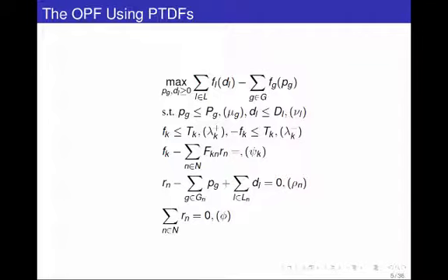So R as well as F are unrestricted in sign. There's nothing that imposes that they be positive, non-negative, or non-positive. So basically this equation is all of last lecture. The reason we bothered going through all the stuff we did last lecture is to get these linearized equations that map injections to flows. You tell me what the injection is in each bus, I tell you what the flow is. But now I have to worry about whether I'm violating the limits on the lines.